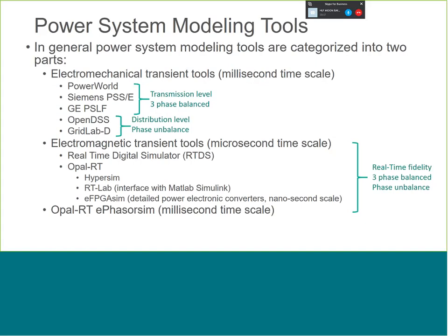On the electromagnetic transient tools, what we have are RTDS and Opal-RT. Tim briefly talked about the capabilities of both, and we are going to discuss a bit more on those tools. Both the electromagnetic transient level tools are real-time simulators capable of interacting with external devices and maintaining the real-time fidelity of the system.